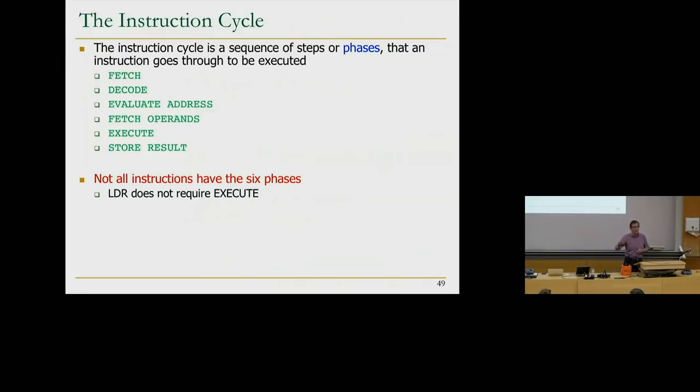This is a simple load of a data value from memory to a register. You need to calculate the address, evaluate the address, but you don't need to execute anything. After you fetch the operand, you directly store the result into the register that's specified as the destination register.